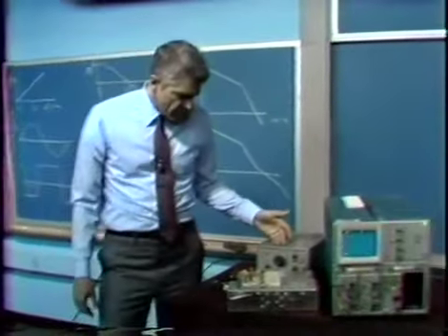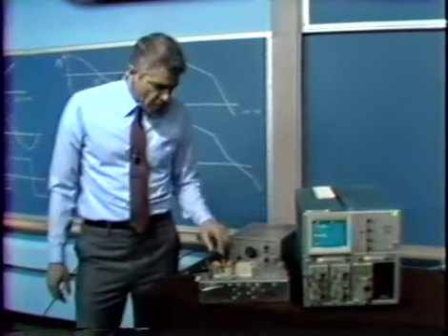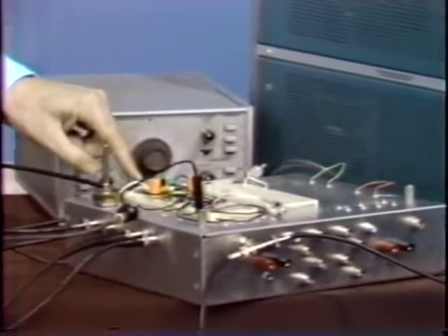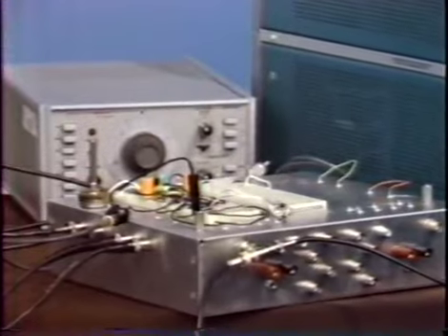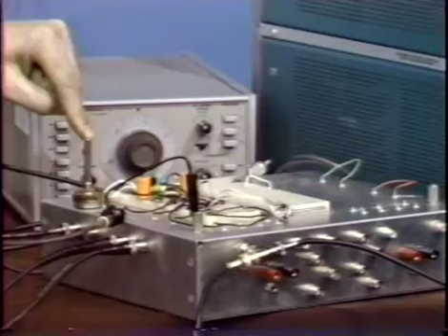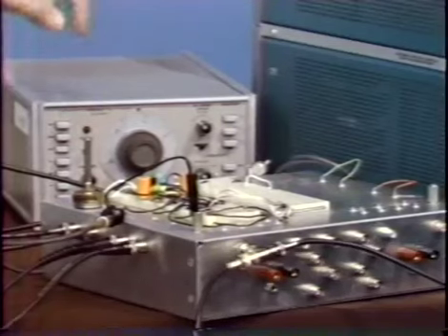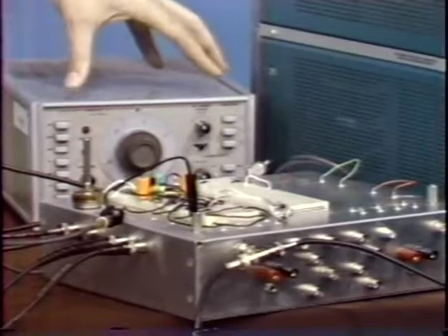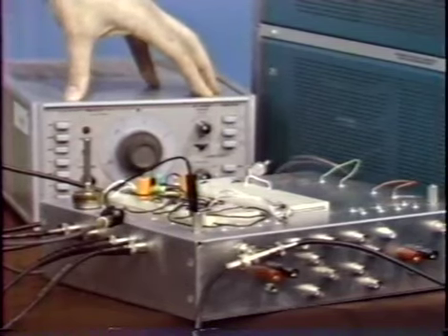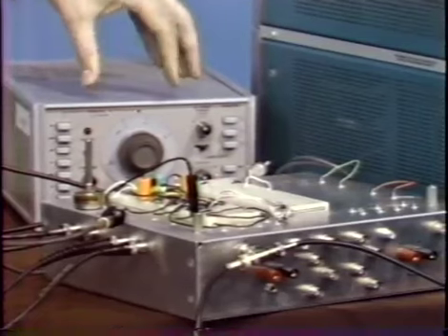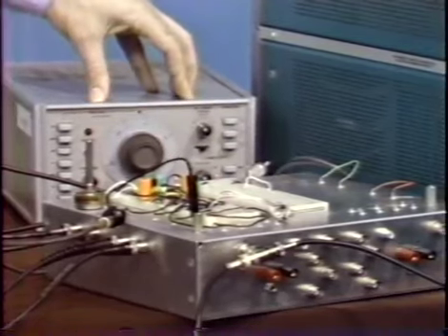Here we have the system we're talking about. Buried in here is the 565 type phase-locked loop chip and some of the peripheral components that we need. This is the potentiometer that's mechanizing the resistor function that I had mentioned. We're driving the whole thing with an external voltage-controlled oscillator. So this box is a function generator which can in fact be voltage-controlled, and we can use that function to put in changes in input frequency.